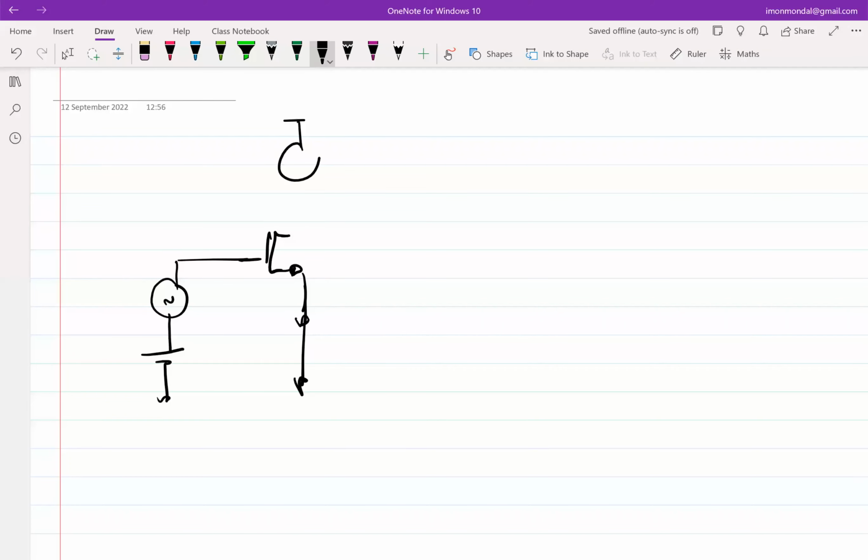So I take a current source, ID or I0, let's say, and I bias my circuit, and let's say this is VG. So now tell me, will this work? No. It will not work. Why? Two independent sources are trying to set the same thing, and they are not talking to each other. So what was the solution we came up with? And forget about the biasing, incremental input for now. So what was the solution?